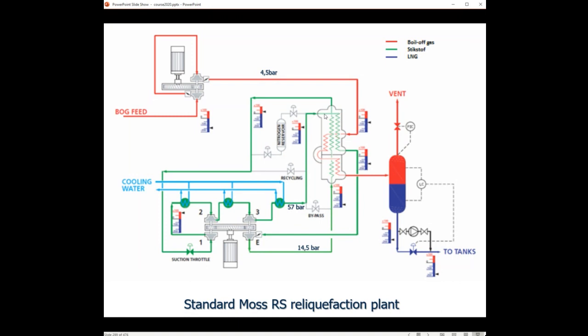The nitrogen is cooled here by the nitrogen which is passing in that way, where we come later on. So this nitrogen goes into the condenser for additional cooling. It comes out of that condenser at a temperature of -110, -120, something like that.